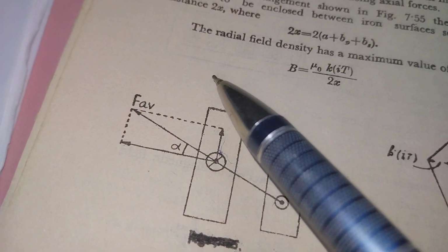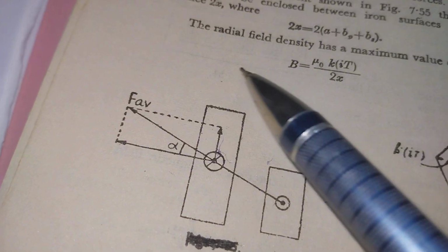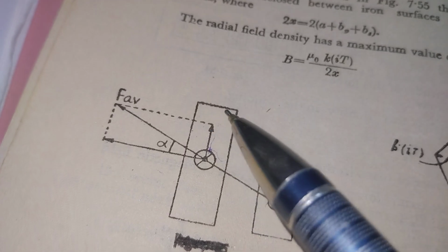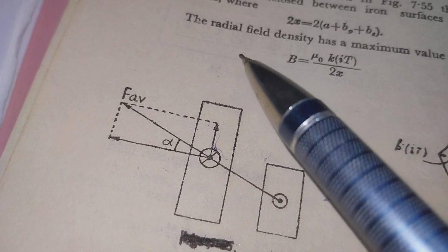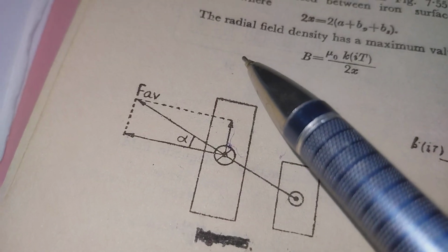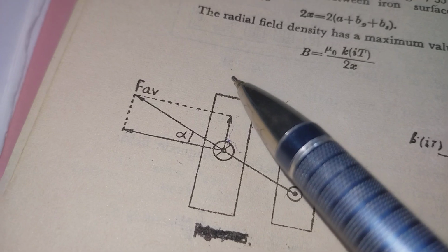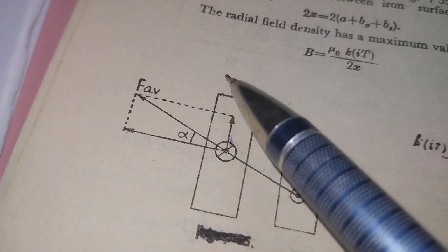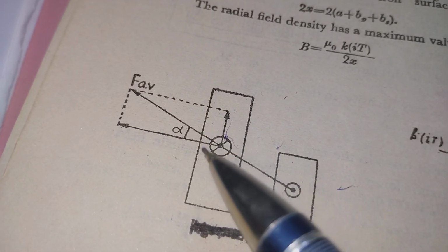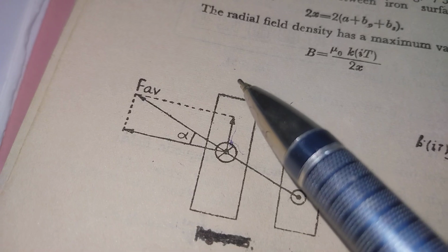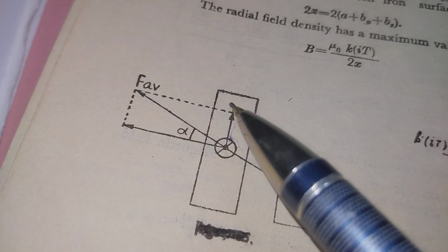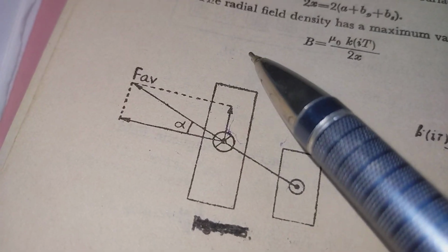If appropriately designed bracing is not placed on this, suppose a 100 mm thick bracing is required, and instead of 100 millimeter thick, 2 numbers of 50 mm thick bracings are applied, in all probability the transformer will fail under short circuit condition due to stress along the axial direction.